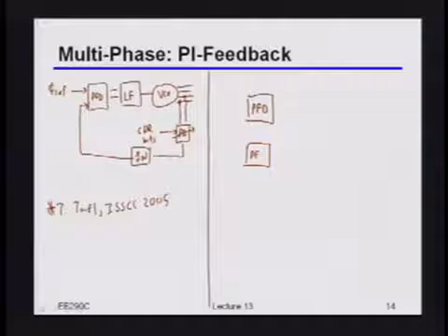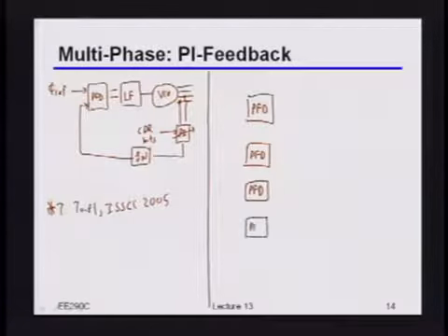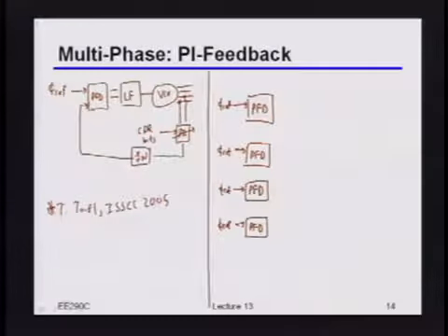Let's say that just conceptually, instead of just having one phase frequency detector, conceptually imagine we now had 4 of them. Okay? So the reference for all of them will always be the reference, right? That I'm not going to change. But now what I can do is, if I actually have 4 phases feeding back from the VCO, I could feed each one of those phases independently into each one of those phase detectors, right? So let's say I had a 0-degree clock, a 90-degree clock, a 180-degree clock, and a 270-degree clock.